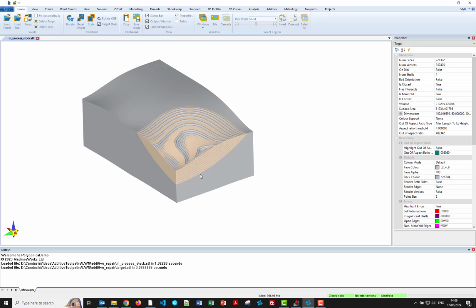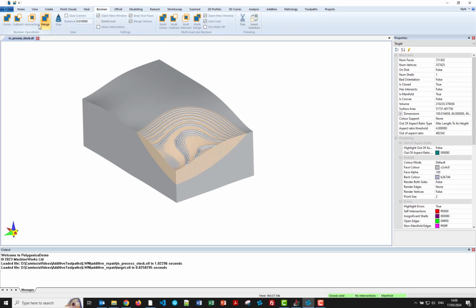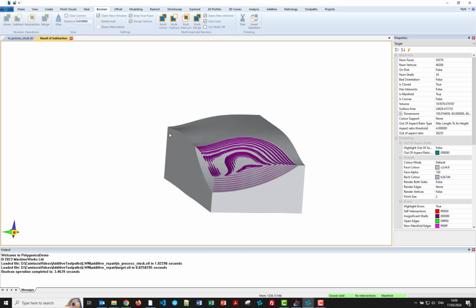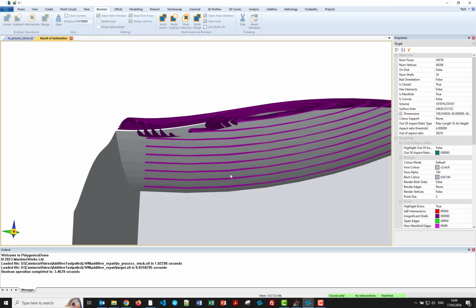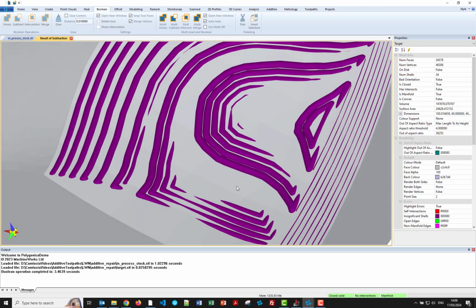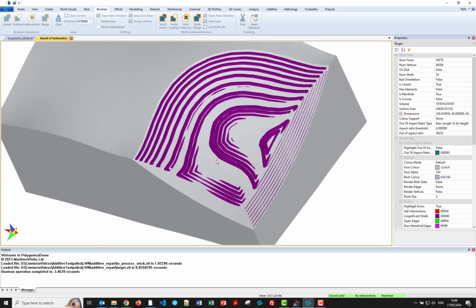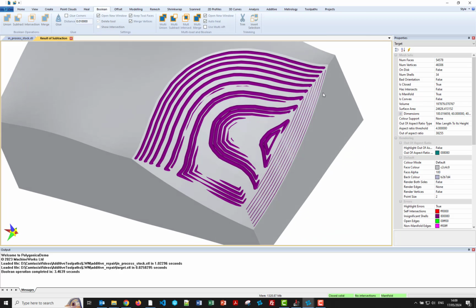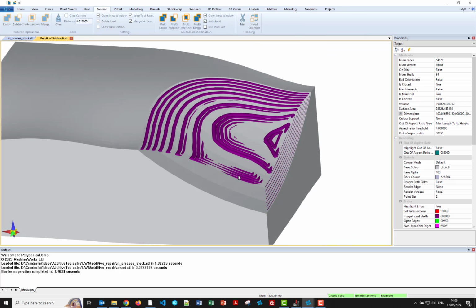And then if I show all again, I'm going to do a Boolean subtraction of the volume we're trying to fill from the volume we have filled, and that will give us this nice sliver geometry, which we can use, for example, to compute boundaries in order to constrain further, say for example, subtractive machining operations to tidy up the surface, etc.